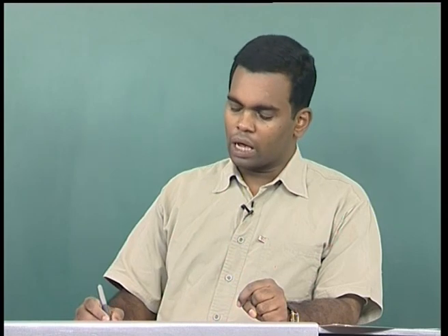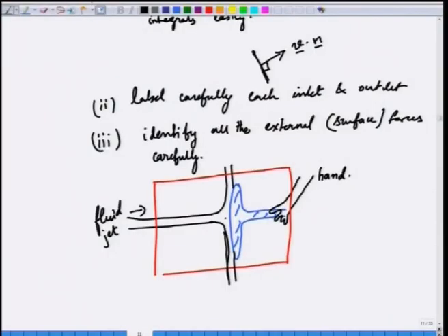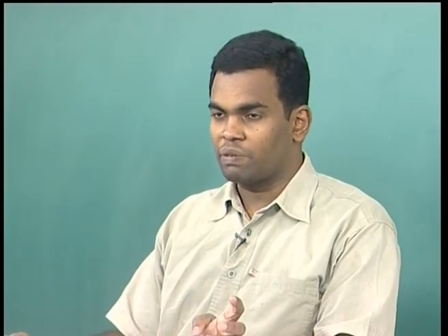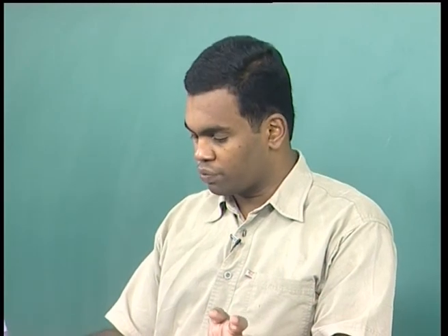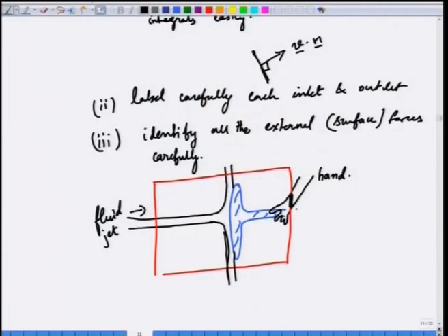Since the solid surface is remaining stationary, the fluid impinging on it will induce a momentum transfer to the surface, which will have to be resisted by an external force, which is a reaction force from your hand. So, this must be included as a surface force, because there is no other way we can account for it. This is not a body force; it happens only at the control surface, where the control surface cuts across your hand. So, that must be incorporated as a surface force.